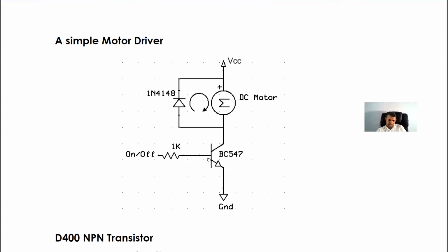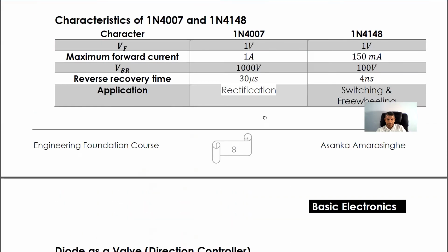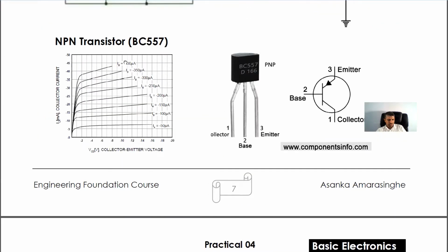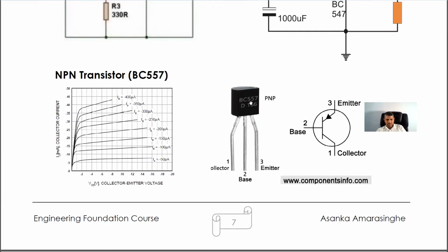this circuit. You see, this is a simple transistor, a BC547 transistor, let's say. From the supply voltage to the collector, I have put a DC motor. Then the motor can be turned on and off by providing some voltage to the base terminal, right? Because we are going to use this transistor as a switch. And if you remember, in BC547 we can only take microamps.